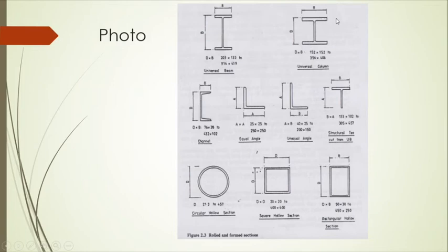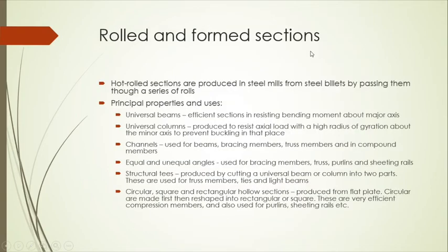So as mentioned earlier, we have a radius of gyration here, and a moment at the minor axis. So you have these sections, this flange, this web, to counteract the rotation on the minor axis, but on the major axis we have both flanges, both webs.